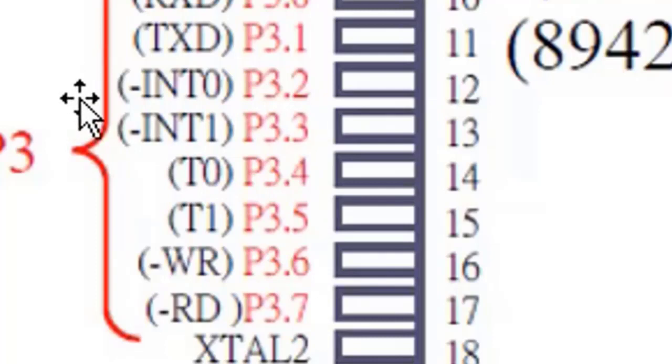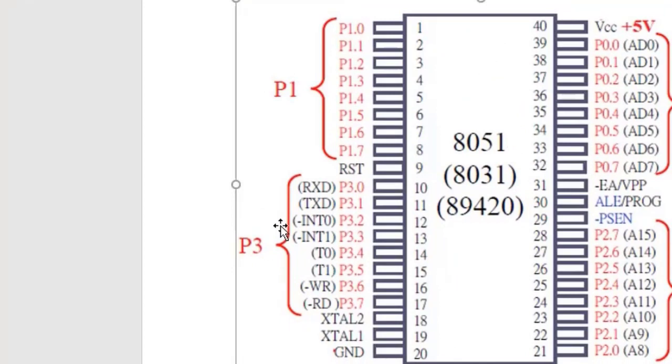Another use of pins 3.2 and 3.3. What is the use? If I want to control the timer externally, in that situation, we must give a particular signal at pin P3.2 or P3.3. When we give that signal, after that, if we use the instruction set bit TR1 or TR0, then the timer will run. This is the hardware control, and to control with hardware, the gate bit in the TMOD register should always be kept as logic 1. So I think it is clear.